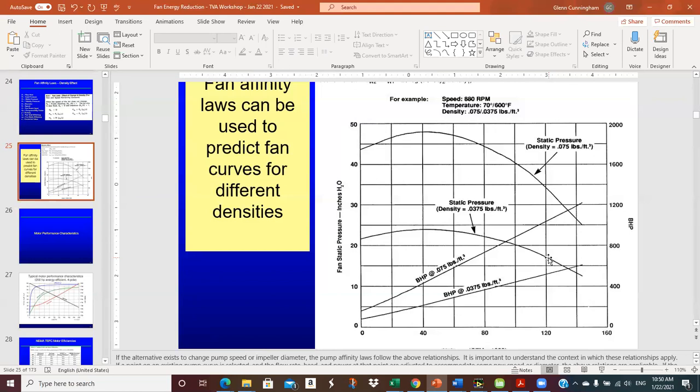Yeah, that's what I kind of figured. Put it in the center, basically. And like I say, try to find the longest straight run you can. And you do need to do a traverse. If you just want relative numbers, you can just measure the center line. If it's a turbulent velocity profile, it's going to tend to be fairly flat until you get close to the walls.